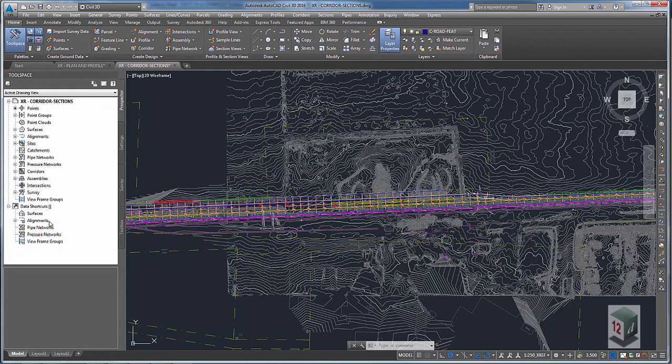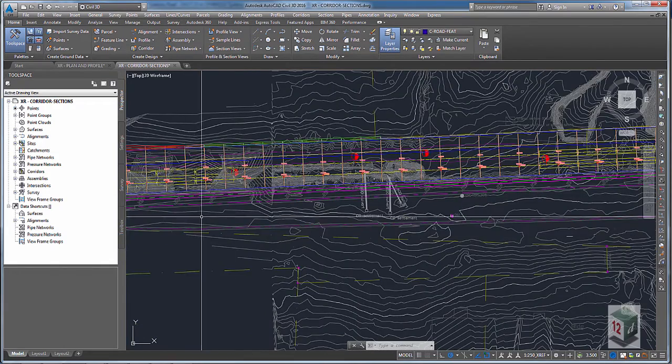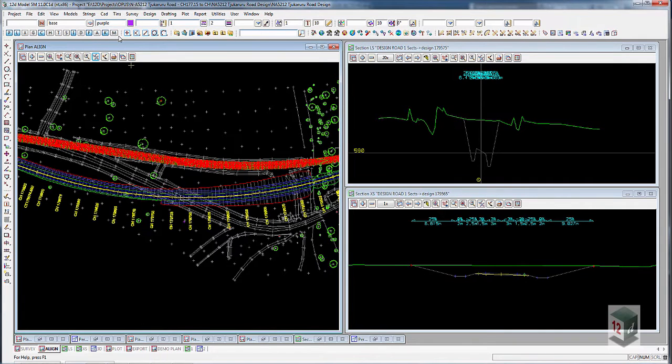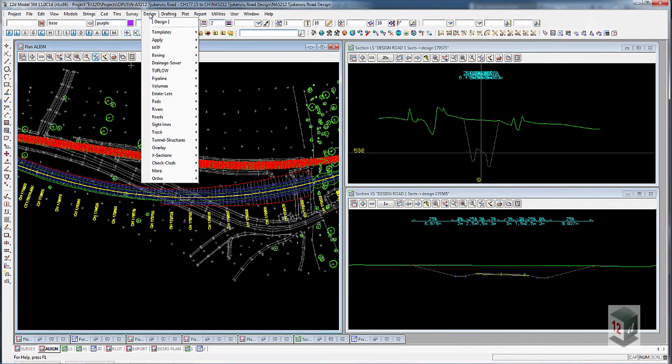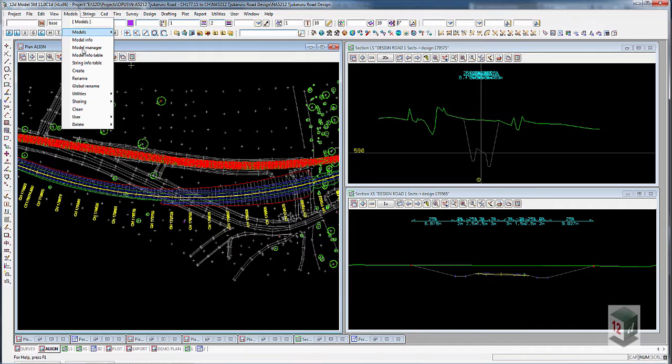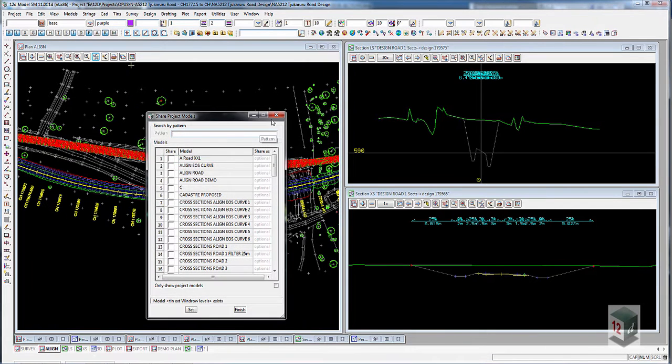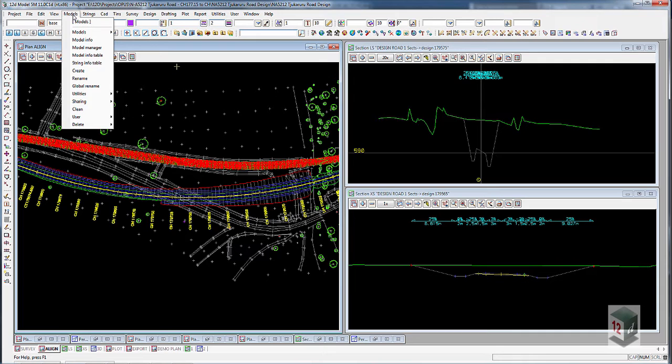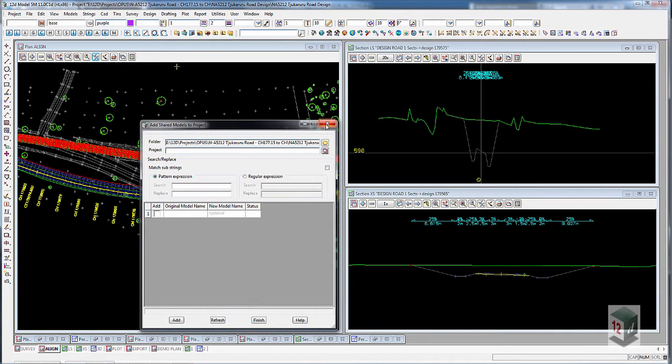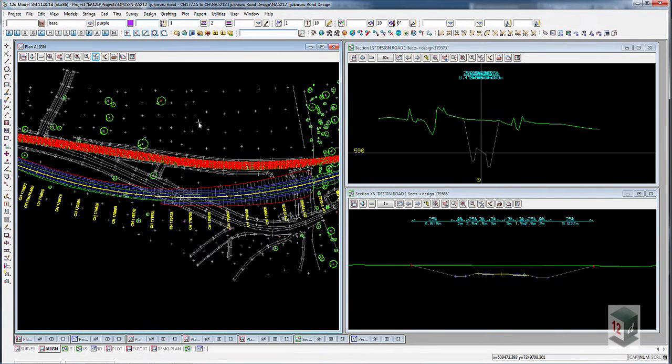Shortcuts in Civil 3D is basically sharing between different drawing files, or sharing models, and 12D has that same functionality. We can share to anything. We just turn on which models can be shared in one project, and then in another project we just add them. If someone updates something in another project, it gets updated in our project. So it's the same as shortcuts.